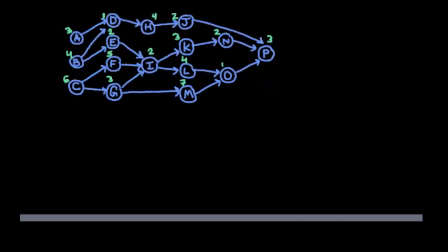So if you had one person doing all these tasks to make the widget, they could only do one element at a time. So you would need to go A, then B, then C, then maybe D, E, F, G, H. Or you could switch up the order a little bit, but you could only do one element at a time. So total, one person making this widget would take 3 minutes, plus 4 minutes, plus 6 minutes, plus 1 minute, and so on, all adding up to 52 minutes for one widget, almost an hour. But we want this assembly line to speed things up. I'm going to say our goal is to get one widget out every 10 minutes.